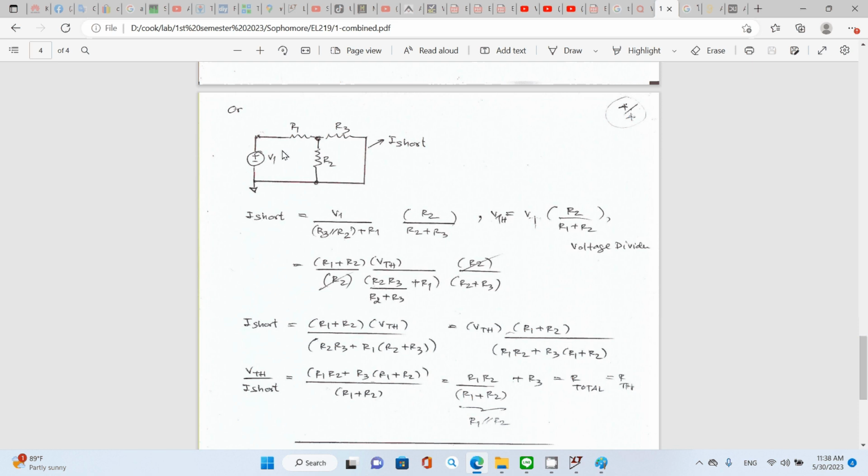So this is your current flowing through R1, and you need to divide it into R3 and R2, or IR3 plus IR2, the outgoing current. That's going to be equal to the incoming current, or IR1. That's the KCL, right? Kirchhoff's current law. And for the current divider, you need to multiply by R2, not R3. You already know about it. You studied physics, electrical circuits, when you were a freshman, the first year student.